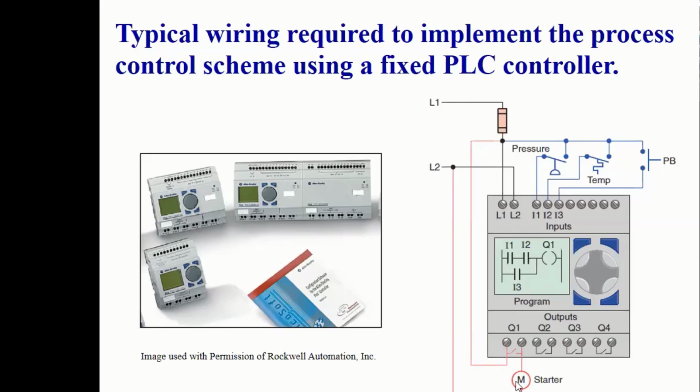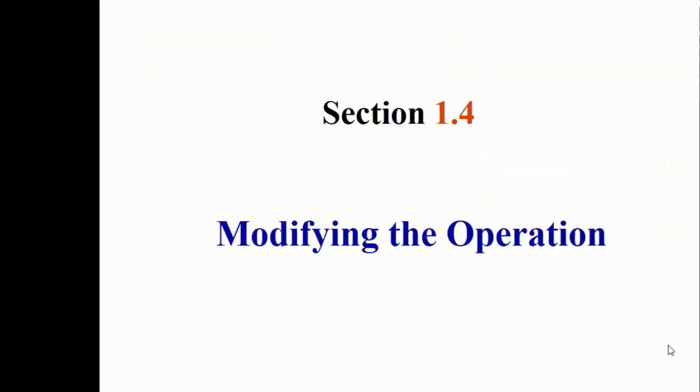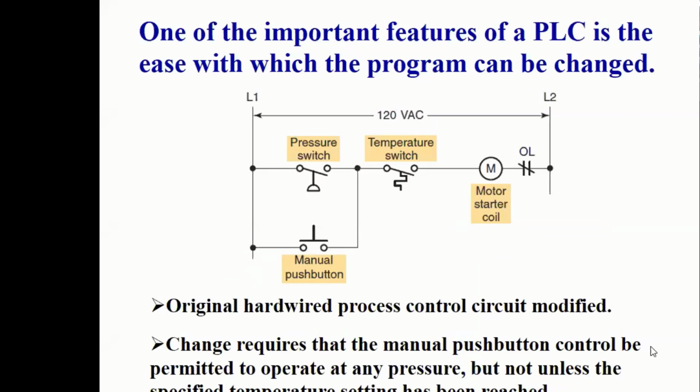And then you have a way to connect and control the output, which in this case is the coil of the motor. To make a good distribution of your electrical circuit and not overload one single line, it's a good idea to balance that load. You can see that the inputs are on L1, whereas the outputs are on L2 as a way to balance that.